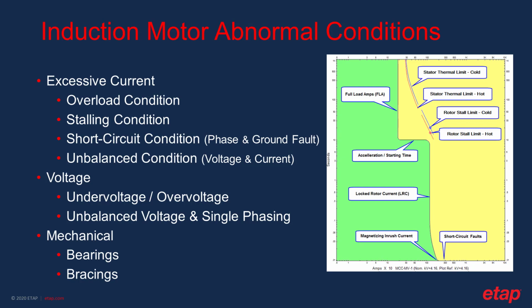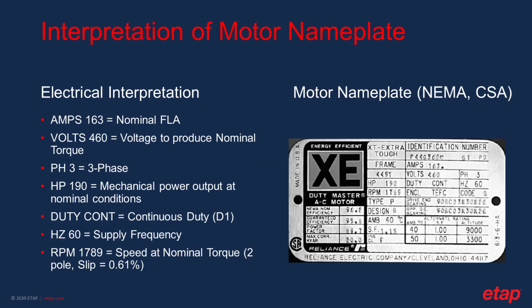To plot these curves, we need the information from the manufacturer, and if such information is not available from the manufacturer, especially in relation to the operating curve, another option is to have the nameplate data of the motor, if it is an existing motor. So the protection engineer needs to have a proper understanding of the nameplate data and how it can be translated into motor characteristic curves.